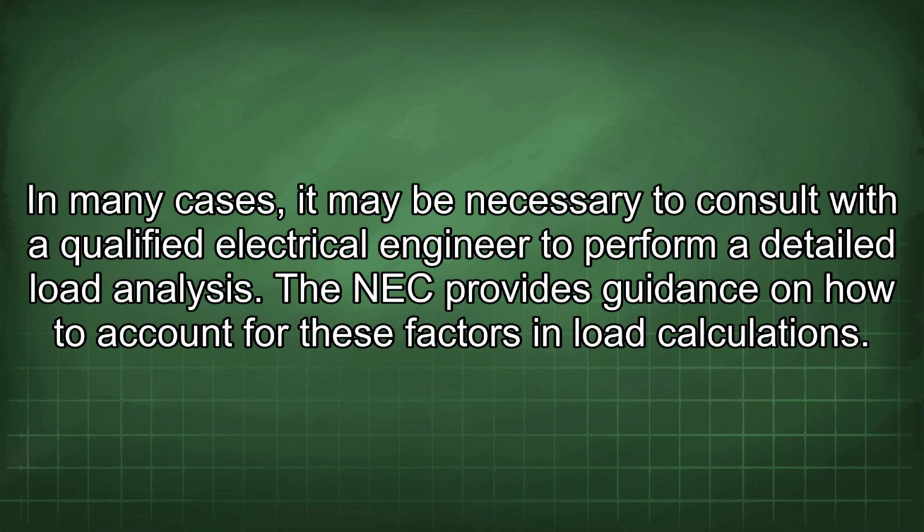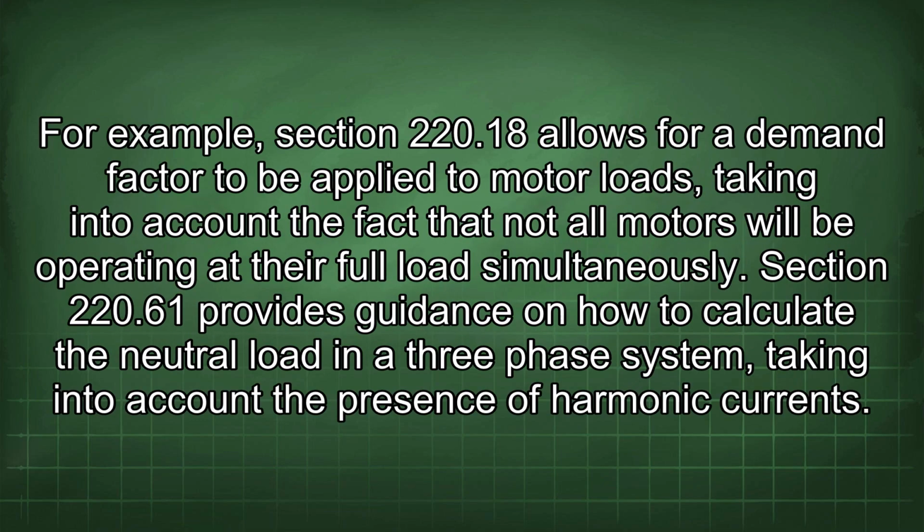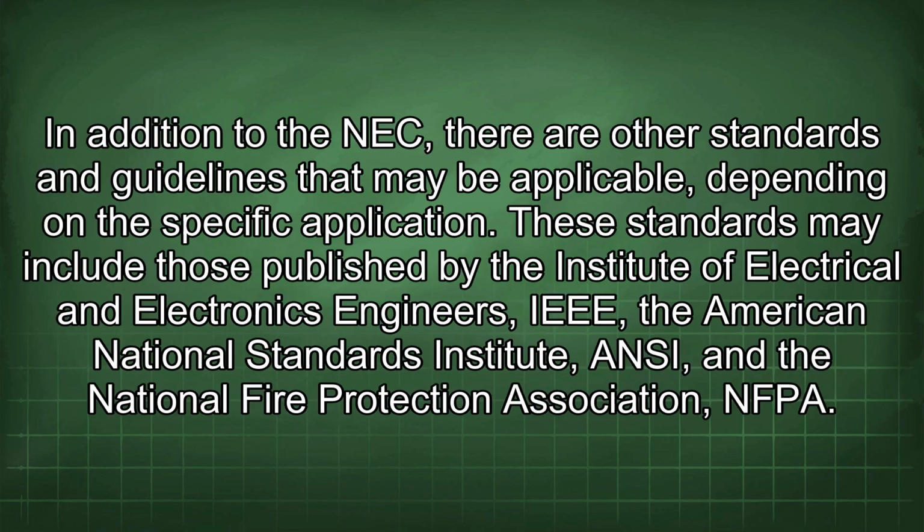detailed load analysis. The NEC provides guidance on how to account for these factors in load calculations. For example, Section 220.18 allows for a demand factor to be applied to motor loads, taking into account the fact that not all motors will be operating at their full load simultaneously. Section 220.61 provides guidance on how to calculate the neutral load in a three-phase system, taking into account the presence of harmonic currents.